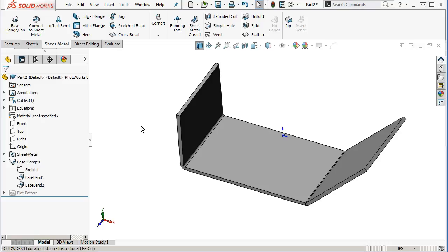Yeah, I think the drawing that I'm thinking of had something like, part shall conform to final dimensions. The final fit dimensions, yeah. And then the flat pattern is for reference. Yeah, but on the other side of that, those final fit dimensions are going to be open dimensions, and once it's bent, you can't control it anymore. What are you going to do? Unbend it? I guess they would make one, right? And make one and check it, and that would be where you'd start to accumulate your bend allowances.